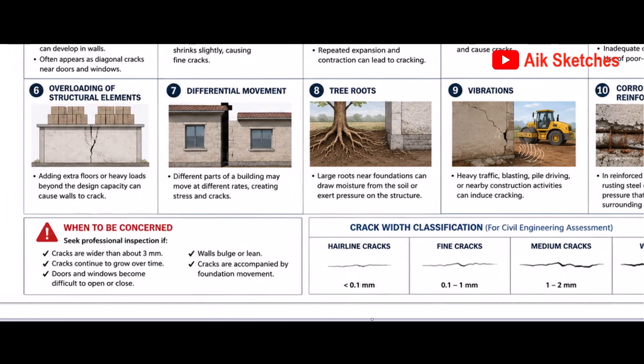I'm going to be reading a little information on your screen. It says when to be concerned. Seek professional inspection if cracks are wider than about 3 millimeters, cracks continue to grow over time, doors and windows become difficult to open or close, walls bulge or lean, or cracks are accompanied by foundation movement.